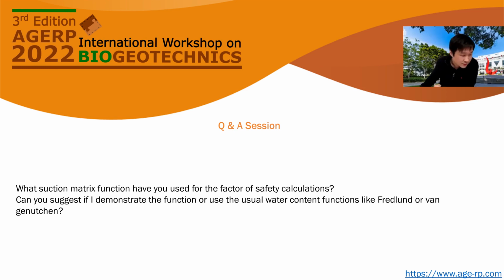Yeah. A suction function, I suppose you meant the water retention curve. Now, the water retention curve is by a modified Van Genuchten equation. The classic one is Van Genuchten in 1980, but then I used the Gallipoli modified version, which takes into account deformable soil in that Van Genuchten model. And then I further elaborated by introducing the varieties of rooted soil into this model. So it's neither purely a Gallipoli type nor a Van Genuchten type. But if you are referring to the permeability function, I'm just using a pure Van Genuchten, nothing modified. The only modification is on the saturated permeability using this empirical equation.